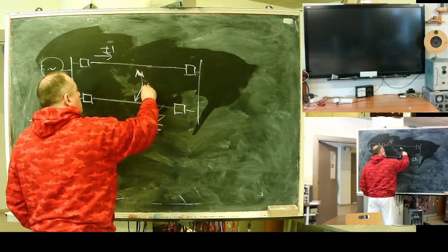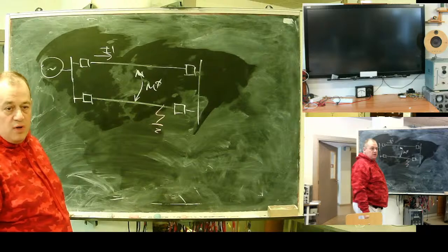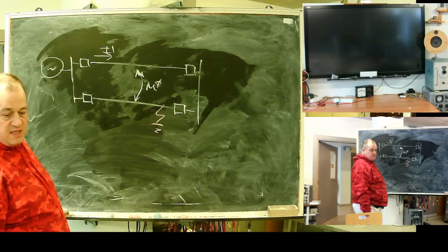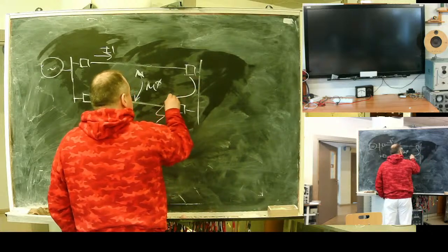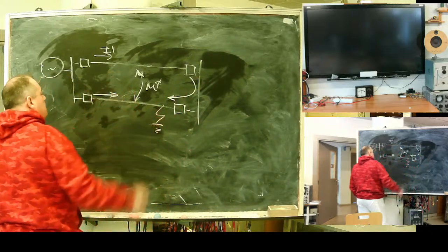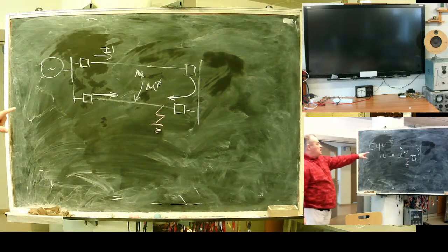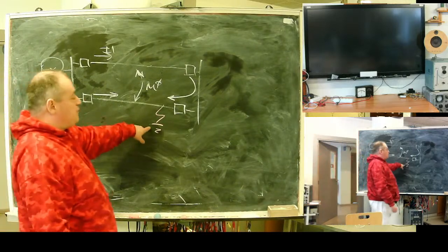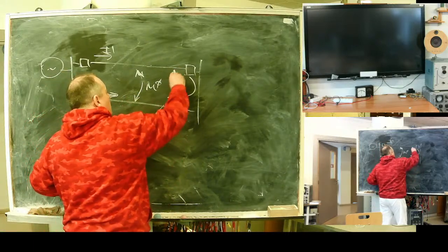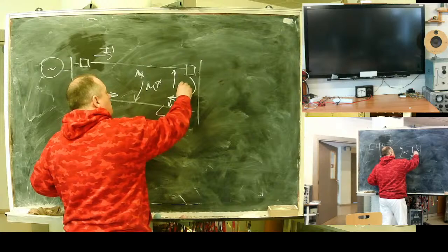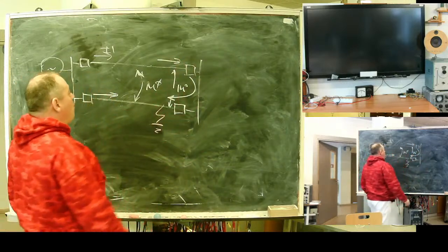Only zero sequence coupling counts. Only in zero sequence schematics they should be accounted. In such kind of schematics, parallel lines, in case of internal fault, there will be a path with opposite current flow.